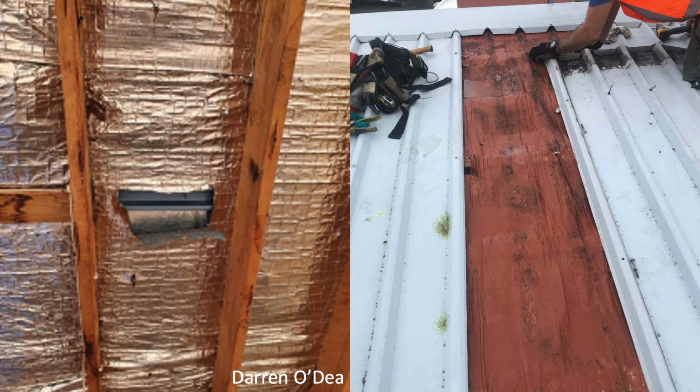Foil, by the way, is a really bad product to be using in buildings. Great for heating up things in the oven, but definitely shouldn't be used in buildings. There's no reason to use foil. That's a whole other topic. We won't delve too much into that. But the issues here relate to the expansion and contraction, and it's a very fragile material as well. So once it starts to tear, it will continue, and then it's effectively useless.